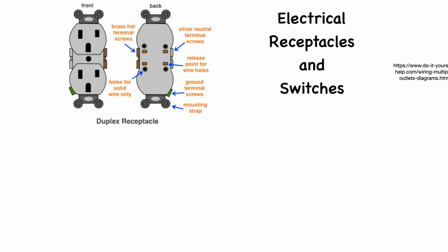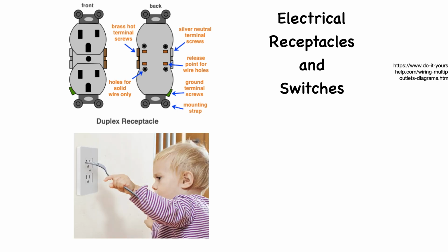As of the 2011 National Electrical Code, most new and replacement receptacles must be tamper-proof. This requirement is designed to protect small children from injury by preventing the insertion of objects other than electrical plugs into the receptacle contacts. Some exceptions to this requirement include wall receptacles that are more than 62 inches from the floor level and large appliance receptacles that are located out of reach.